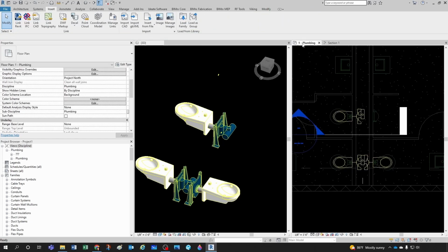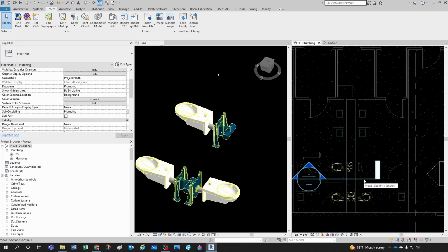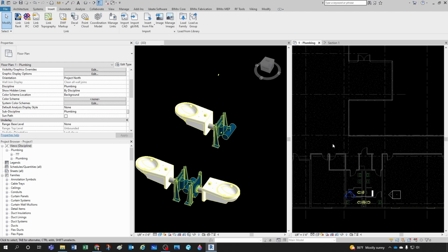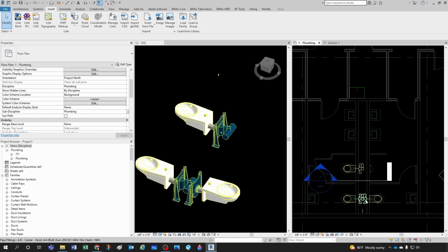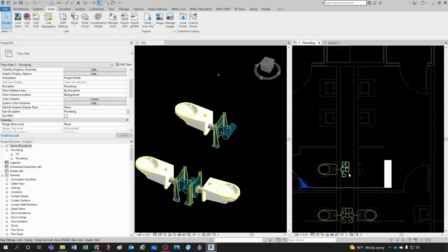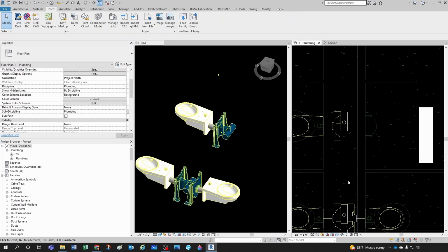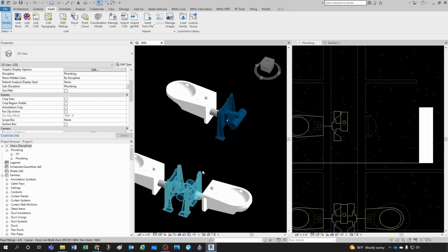One thing I'm going to tell you is that if you're coordinating a very large ceiling space and you're navigating your pipe run throughout that ceiling, and it's a very long run, then you're dropping a lot of invert, right? But if you just have a short chase like this one, and it's your chase, you have nobody else here, you own this chase, sloping pipe is just wasting your time. So in this case I'm not sloping it. You're welcome to do it if you want to waste time, but in my case I don't really have too much time to waste.